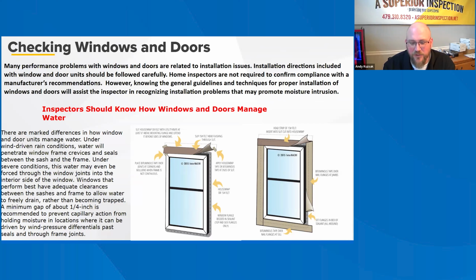In my experience, when you have two windows side by side and you have that plastic mull joint that goes in the middle, that is, for whatever reason, especially susceptible to moisture intrusion. So in and around those windows that have those mull joints, just pay special attention to your window seal, the wall below it, and if there's any moisture staining.